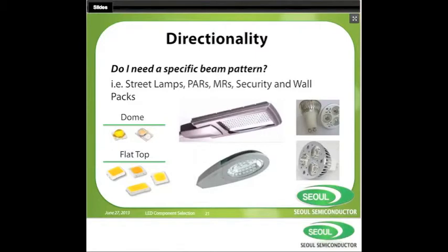I've shown a picture of a couple of different types of LEDs on the left-hand side of the page. There's what we call dome top and flat top. Typically, domes are going to work better with the secondary optic, so it allows you to focus that light a little bit better. As you can see on the right-hand picture, you've got 3 LEDs, and you have a secondary optic on each one of those LEDs to focus each of those LEDs in a system.